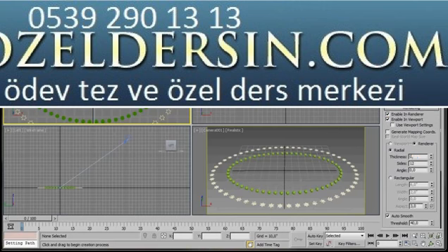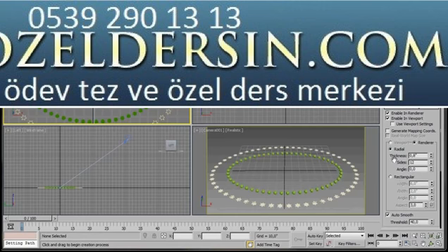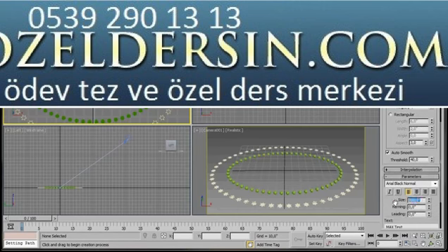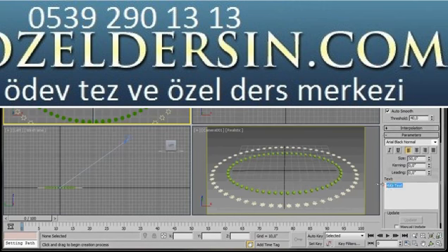In thickness, I'll type in 0.8. And now I'm just going to scroll down to the size. I think I'll type in 50. We'll try 50. Text, we're going to delete Max Text and type in GLOW in capital letters. Just click in the center of the top viewport. I think we can bring that down a little. Let's bring our size down to 45. Oh, I think that's a lot better.